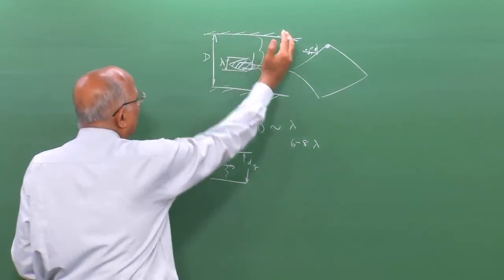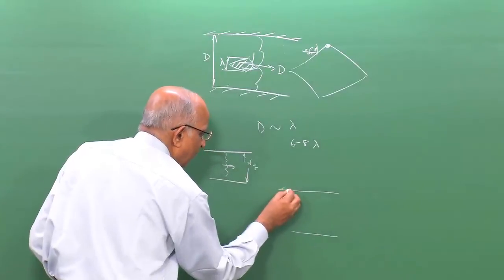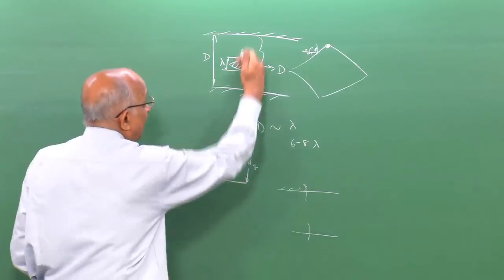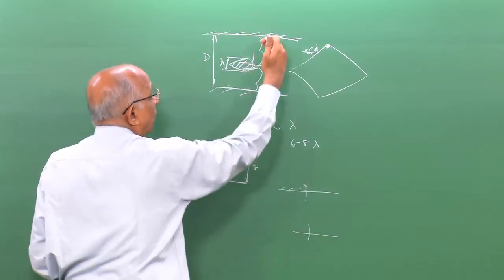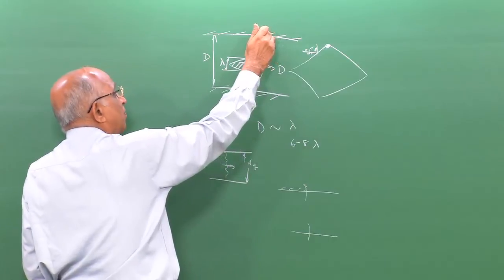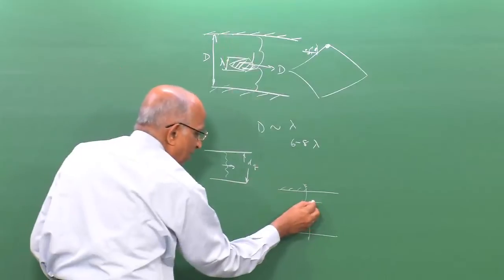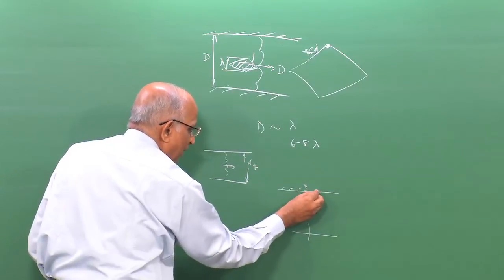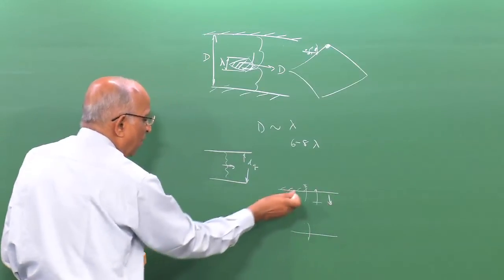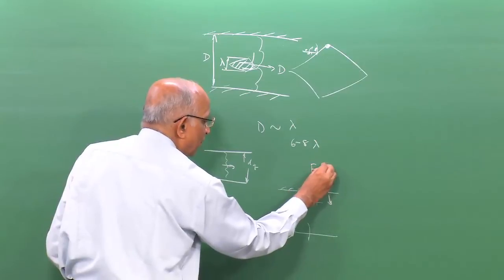If along the wall of the pipe I put a surface which can absorb the lateral waves, since waves are going up and down, a low impedance material which takes the wave, then a wave which comes here is absorbed and no longer reflected, and in this case also the detonation wave fails.